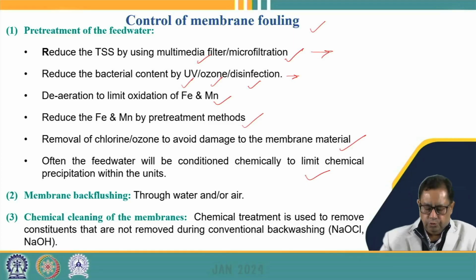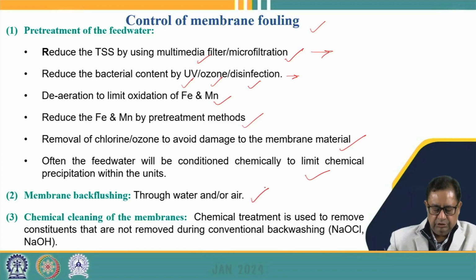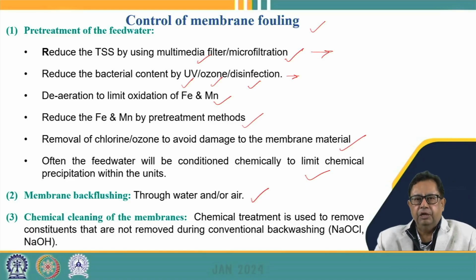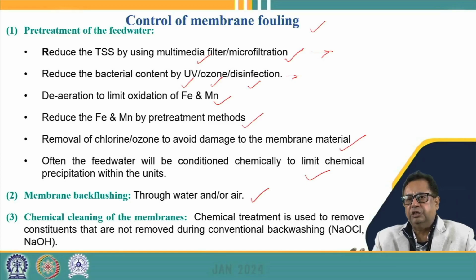But we can also go for backwashing or back flushing of the membrane when it is being used in the process. For example, we can pass pressurized water or pressurized air in the reverse direction, so that we can get rid of these materials.